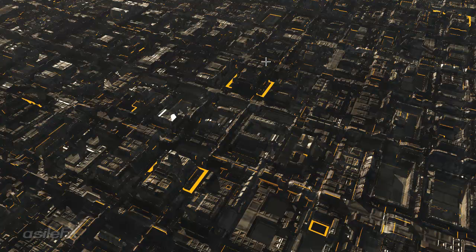So we can also go through and add additional layers to cover different slope ranges. If we wanted to add some strip lights on the side, you could reduce that slope range a little bit more. But you can see it starts to get really interesting when we start adding these additional layers. And of course, you can add as many material layers as you want as of version 6. And then if you want to cut stuff out or place different colors and transitions into different materials, using the slope is a great way to do that.